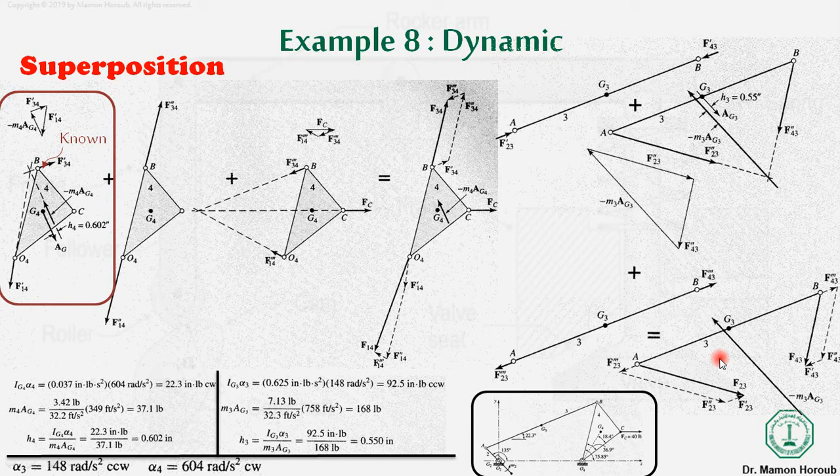Every component is known to us. So over here, if you can see, we have used the superposition principle, which states that, let's suppose on one link you are calculating the reaction forces, the total forces that will be on that body due to more than one force. What you can do is consider one force at a time and neglect the other forces at that time, and the effects due to the individual forces will be added, and it will give us the overall effect.